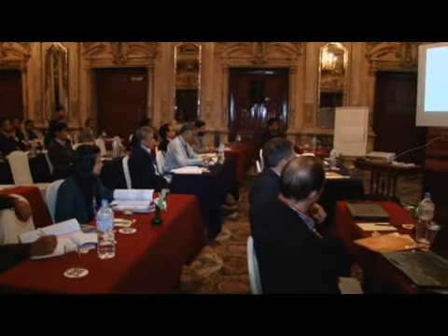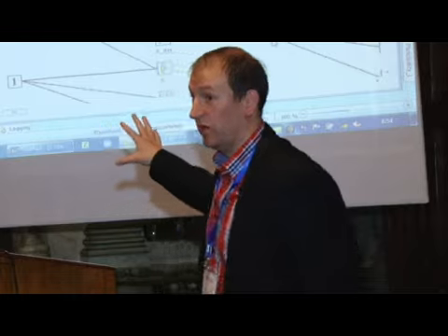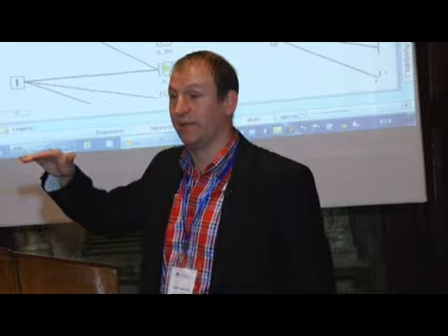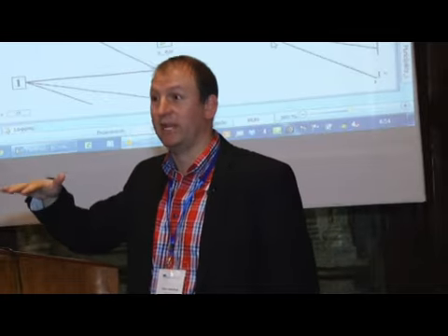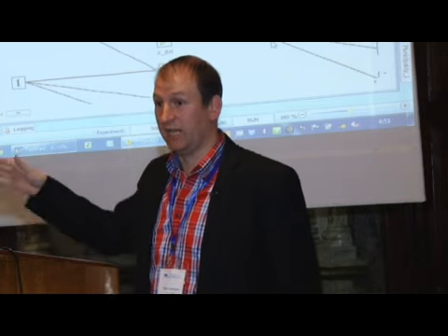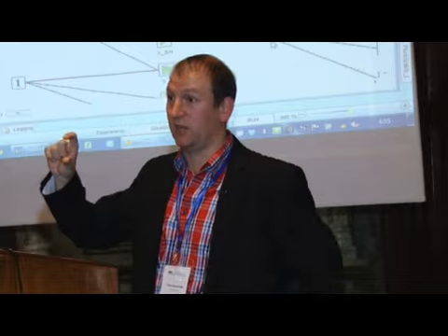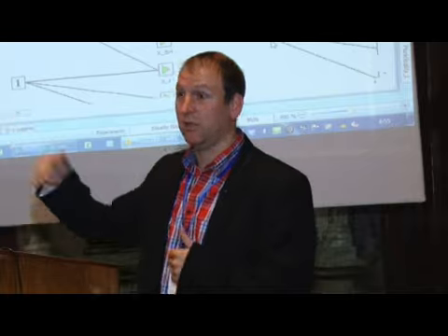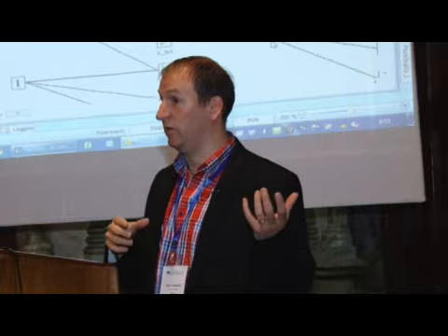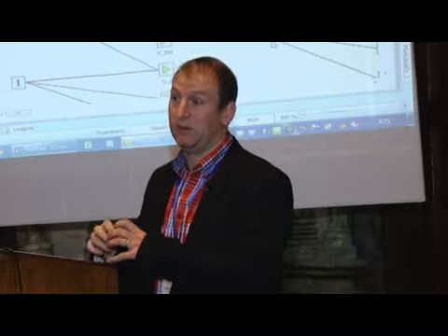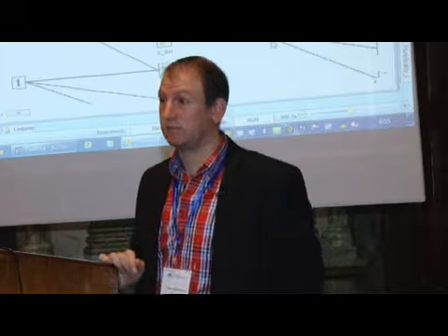Maybe we can take a second to take some questions while aspect to address for these kind of software. These are dynamic simulators. So far, I'm only showing the steady state simulations. But after the break, I'm going to show some dynamic simulations, and then you can really use this where you cannot use the design software for calculation, peak demand function, looking at effects of storm events on your clarifiers and so on, which gives you more detail in the design of the plants.